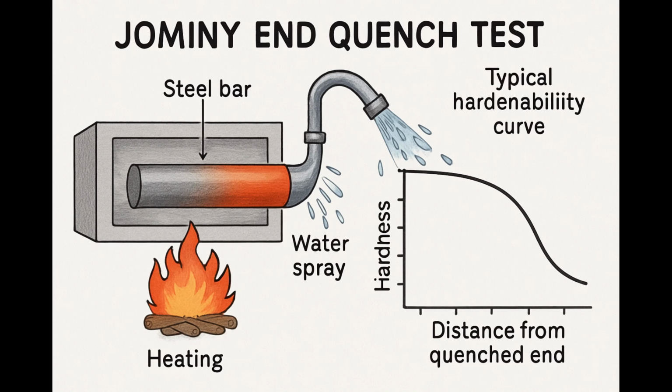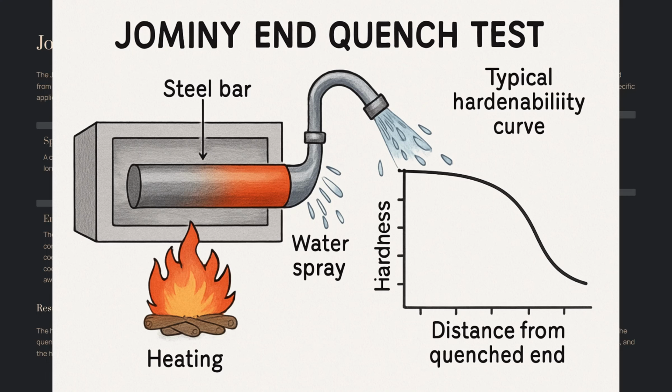Key characteristics. Definition: the ability of steel to harden in depth upon quenching. Distinction: different from hardness, which is resistance to indentation. Influencing factors: alloying elements, most significant; grain size; homogeneity of austenite. Importance: steel selection, quenching medium choice, cost effectiveness. Measurement: Jominy end quench test.